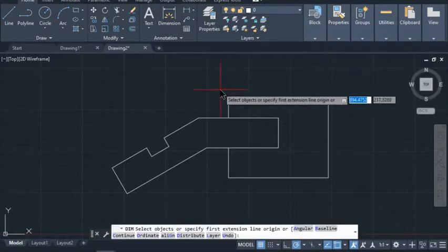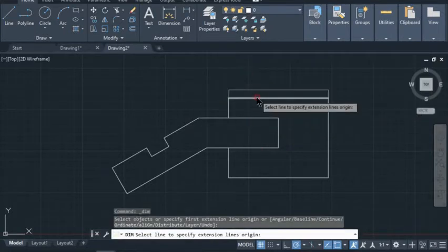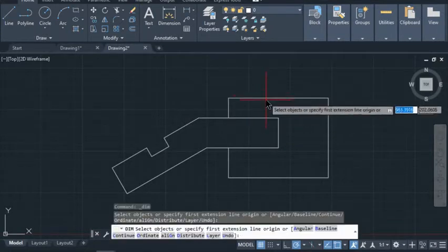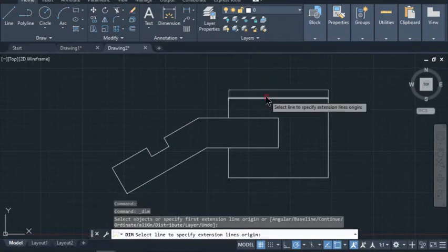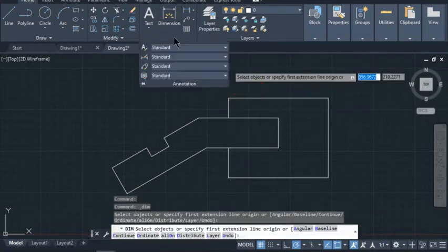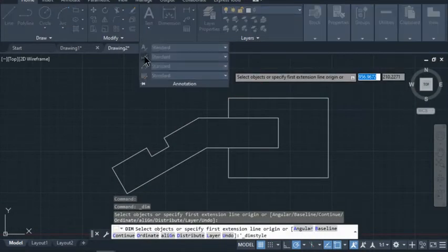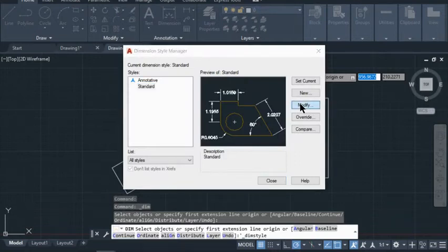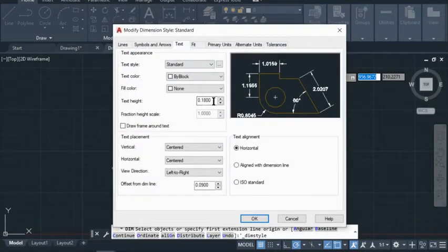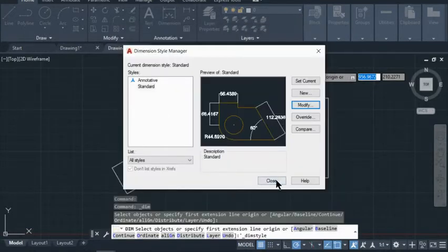And you can go ahead and take out the dimensions. I noticed that the measurement when I do dimension and I put it right here is too small. Remember how you change it? Standard, modify, text, change that to about, let's see, the measurement here is 120, 150. So let's do about 10. That should be big enough. I think maybe too big, but let's see.